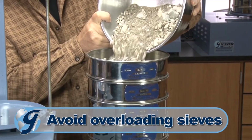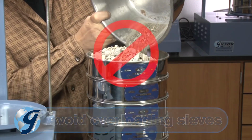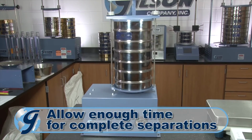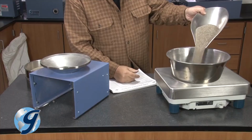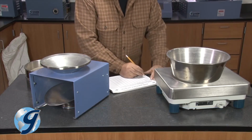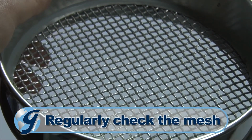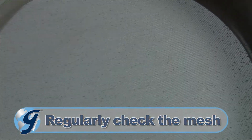Avoid overloading sieves. Total material retained on a sieve at completion should be less than 1 to 2 layers deep. Allow enough time on a sieve shaker or testing screen for complete separations. Watch for degradation. Some brittle or friable materials can break apart during the separation process, leading to inaccurate results. And regularly check the mesh for wear, tears, or distorted openings, since this can bias test results.